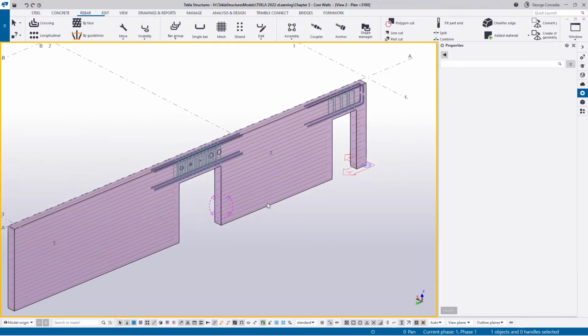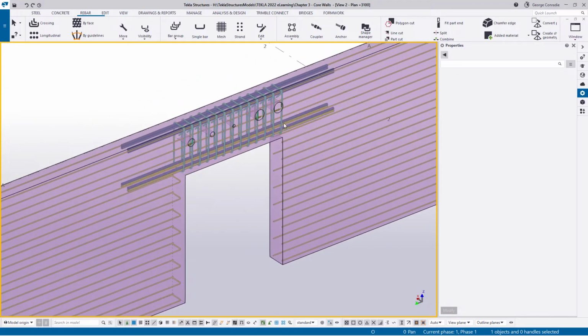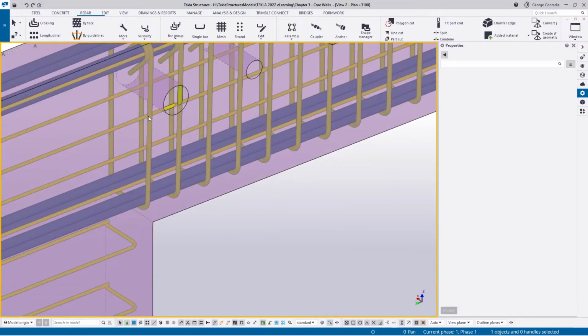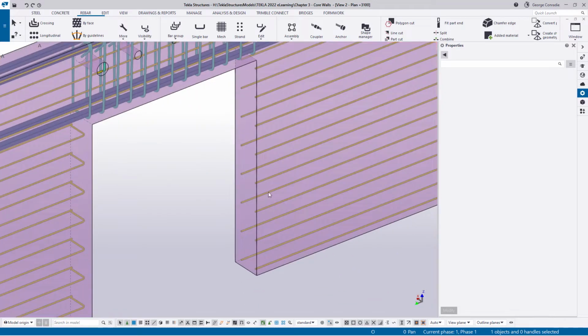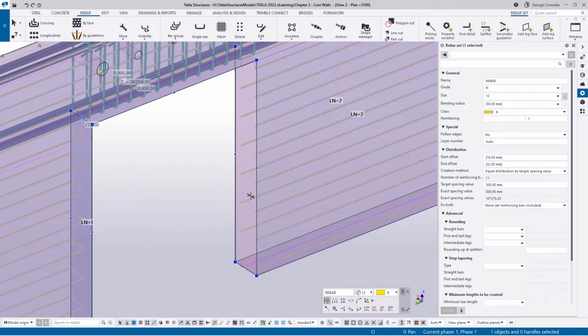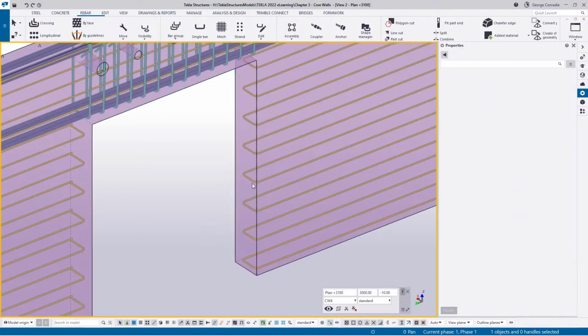although we've got some broken ends here, which we will fix up first. So there it looks like the bars are fine. Yeah, it's going over that side, and you can see how it's put it on the inside of that. We're going to fix that up now. First, we want to click on this bar, and in here we need another face. So while that bar is selected, over on the ribbon we can see add a face. If we click on that and hover over this side, we can add a face, and that sort of fixes up that part.